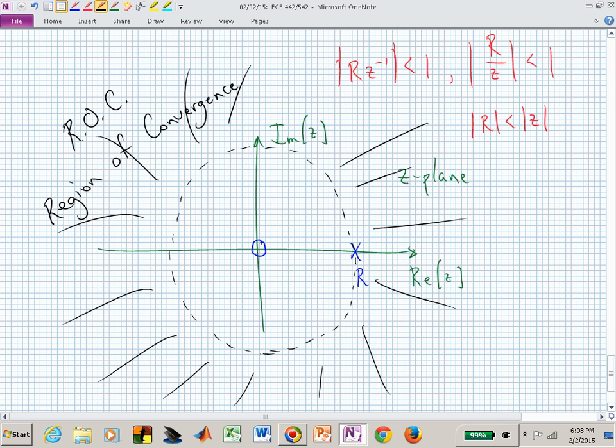Now we have 1, 1, 1, 1. What do we have in the time domain? A unit step. And if that was really a system that had this pole zero diagram where capital R is 1, I could excite that with a constant and it would start giving me an unbounded waveform with time. So people might refer to that when they have poles on the unit circle as marginally stable.